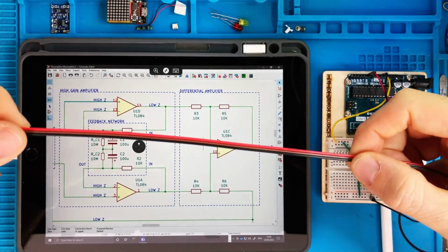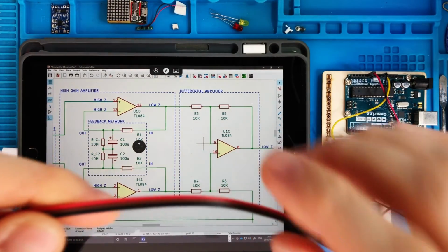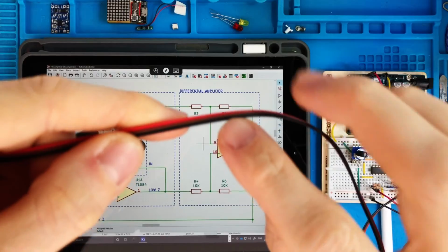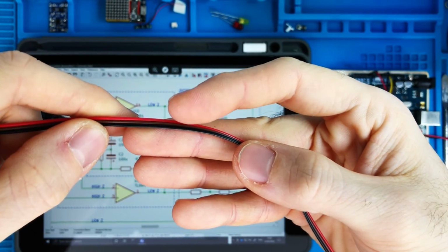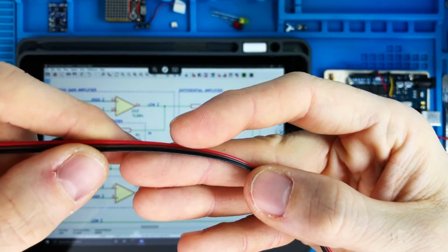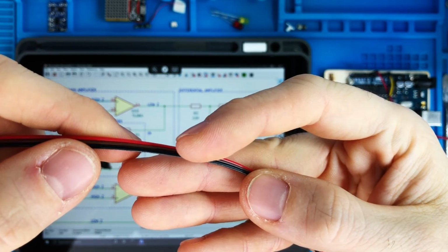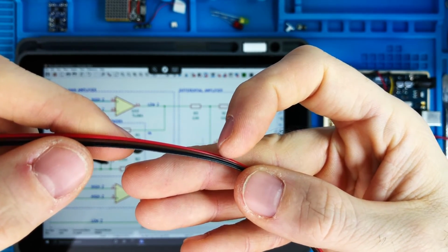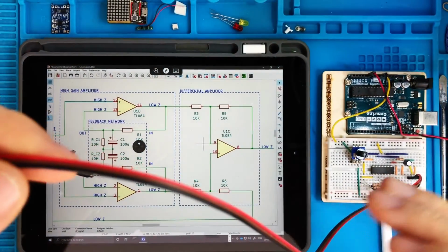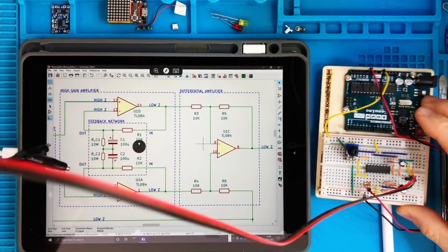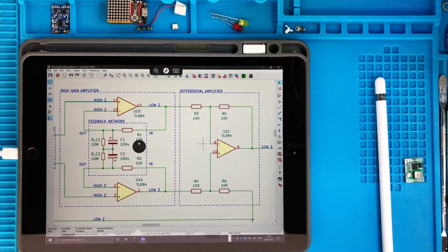This thing is kind of compensated because if there is a noise in the proximity of one of the wires, they are so close to each other that maybe the noise on the other wire adjacent to this is kind of the same, and then it will be subtracted. So this is why it's important to carefully think about the location of the wires when we want to do these kinds of things.